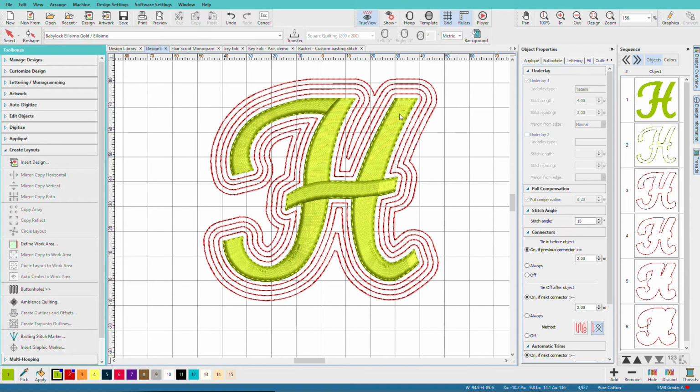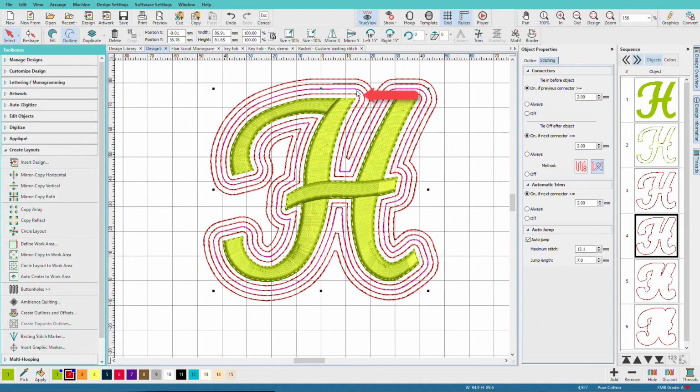There are our outlines. Notice that the green one, which was the one that I selected first at the top of the box, is right on the perimeter of my stitches. And now we have all these red lines. These are our offsets, and I can choose which one I like the best. I would really like to have at least that one, but I don't really like how it dips in right there, so I'm going to choose this outer one.